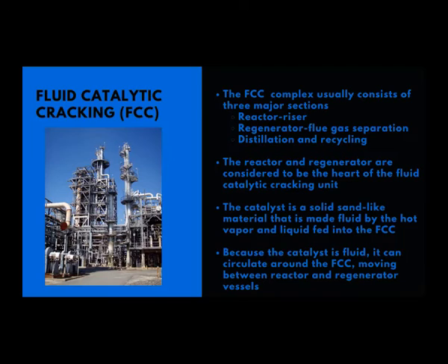So the coke has to be removed and the catalyst has to be regenerated. That is the purpose of the regenerator. Both the reactor and regenerator are positioned adjacent to each other, and continuously the spent catalyst is sent to the regenerator, where the carbon is burnt into CO, and finally the fresh catalyst comes back to the reactor.